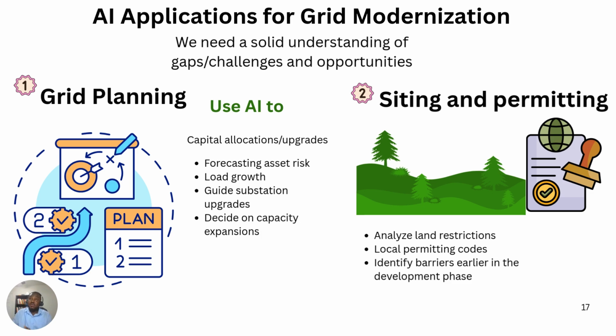But let's say 5 years ago, the transformer loading increased to, let's say, 80%. And now the transformer is loaded 85%, 90%. And you don't want to overload the transformer. So having historical data of the transformer loading will tell whether we need to upgrade the substation or not.